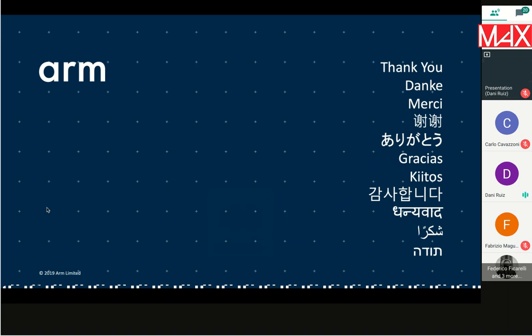The emulator only emulates the behavior of an SVE instruction, but not latency in terms of instructions, or hits or misses in cache if it's a memory access. It only emulates the behavior of the instruction. So if I'm loading a vector, it emulates the load, but it doesn't simulate how many cycles I will spend. That is something you can do afterwards with post-processing.